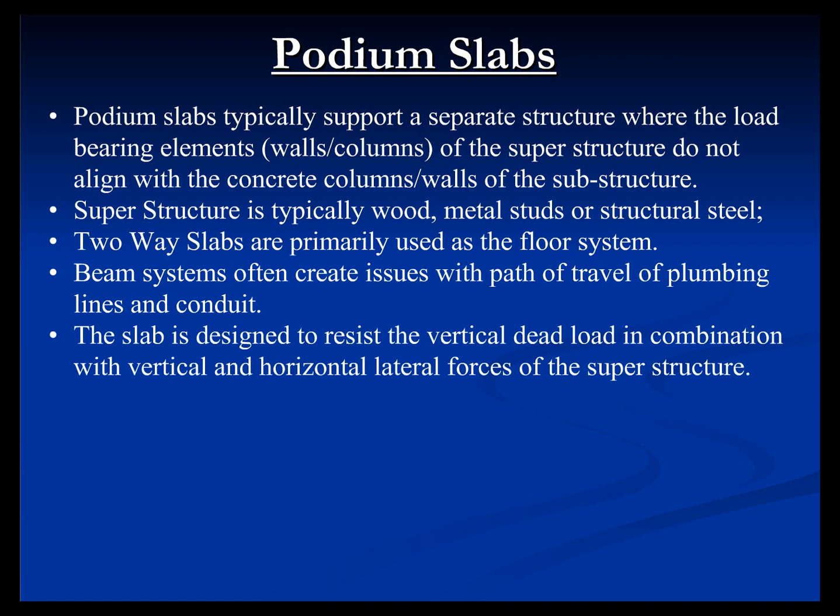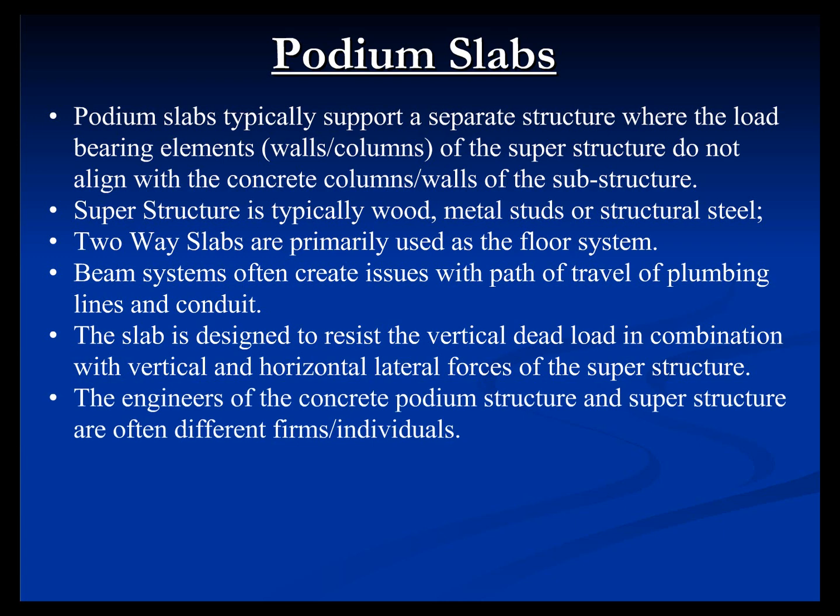The slab itself is obviously designed for the vertical dead load in combination with the horizontal, the shear and the overturning forces of those structures. Typically, for the most part, that is plywood shear walls or metal stud shear walls. Occasionally we have some moment frames for courtyard areas, gym, leasing office, stuff like that, where they don't want walls coming straight down on the structure. And those have their own unique aspects that we will get into a little later on.